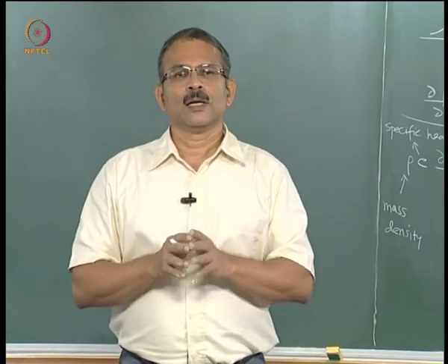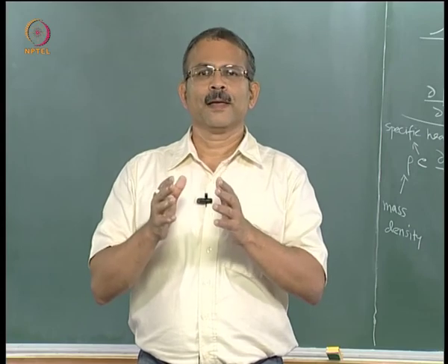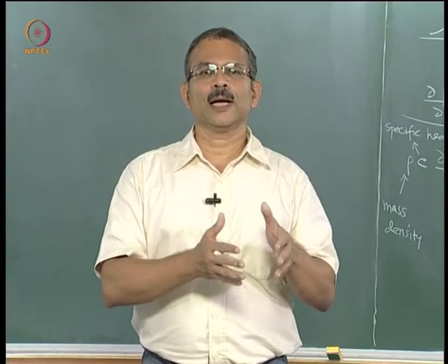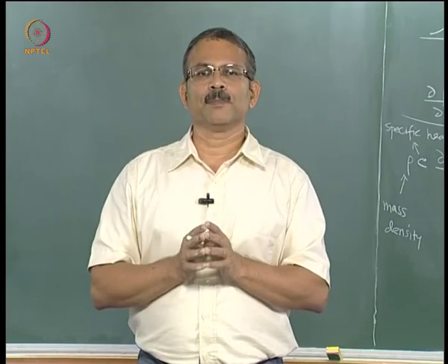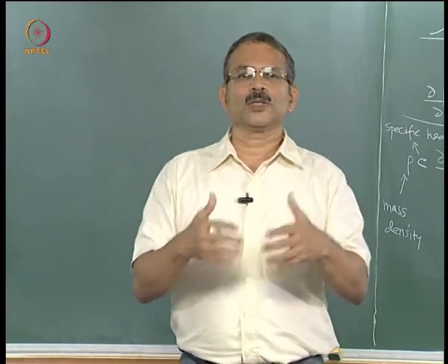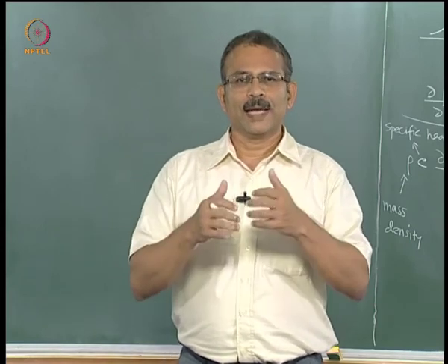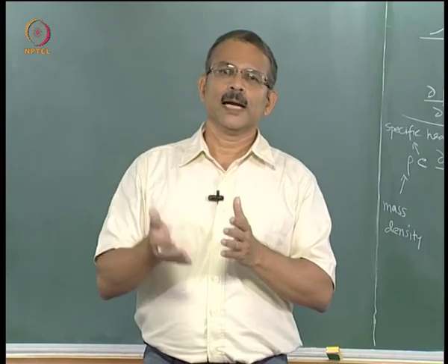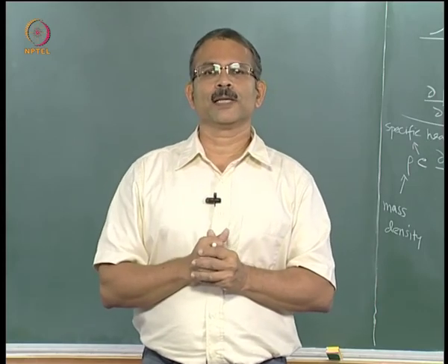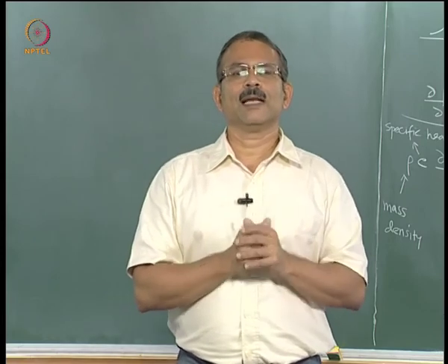So what we said is we could get a solution for f by guessing based on a knowledge of the solution under equilibrium. Under equilibrium the Boltzmann transport equation becomes simple, and it is possible to guess a solution for this simple equation. We guessed such a thing and we showed that the Fermi-Dirac function or its approximation, namely Maxwell-Boltzmann distribution, actually works very well under equilibrium.